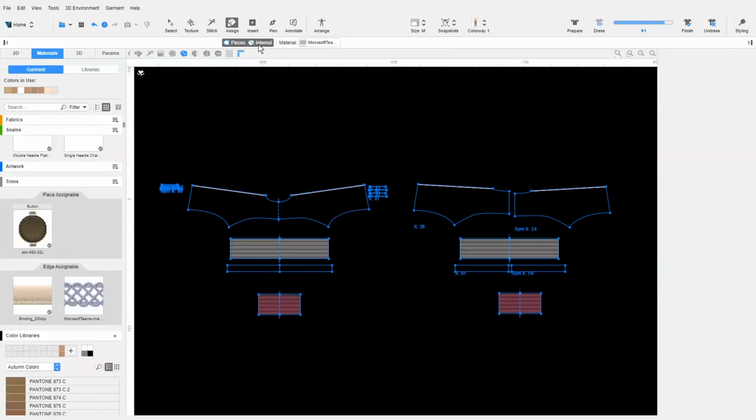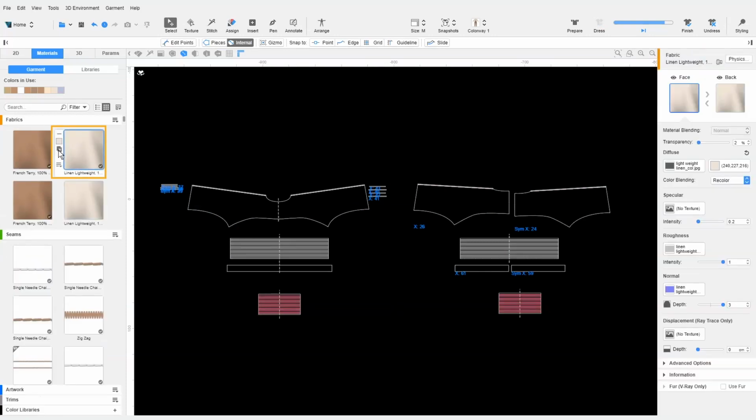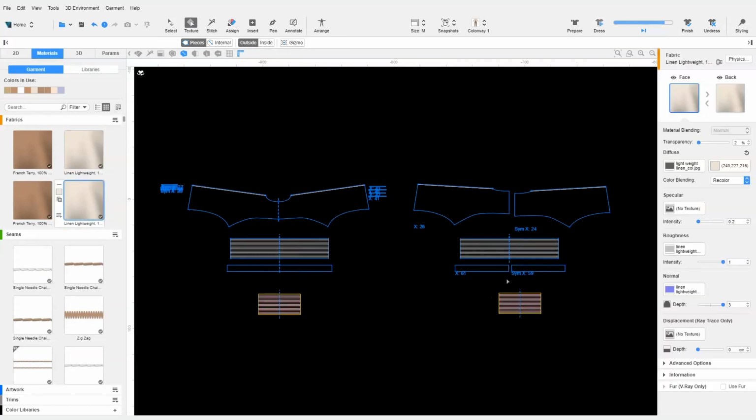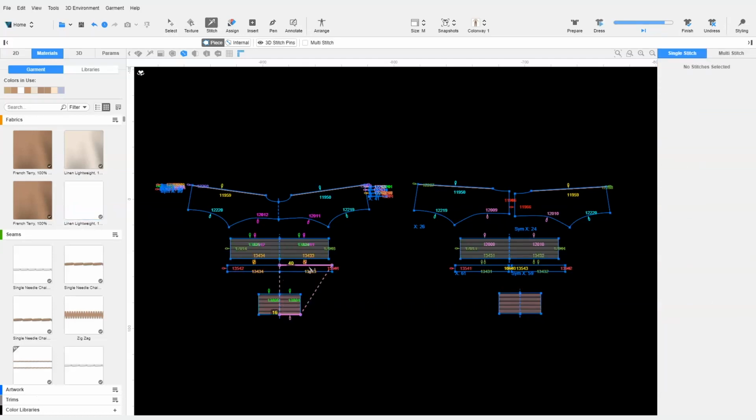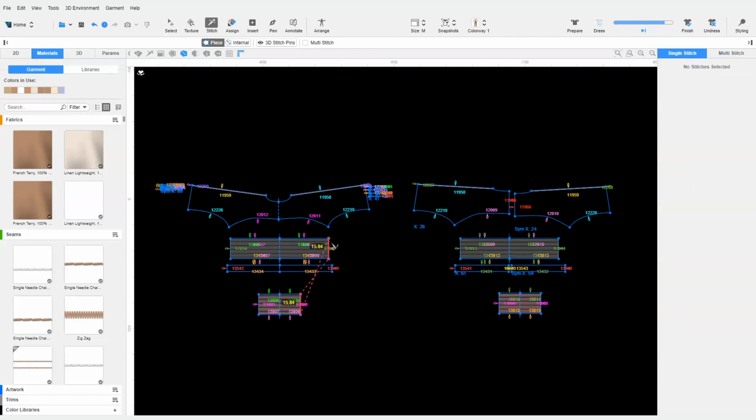Now we do a Clone by Offset to create the internal lines within the pattern. We can now apply the embroidery stitch on the internal lines. As for the fabric, we clone the original fabric and assign the new fabric to these two pieces. Then we adjust the transparency to 100%. Stitch the edges of the patterns to the shirt's pocket. Stitch the side seam as well.